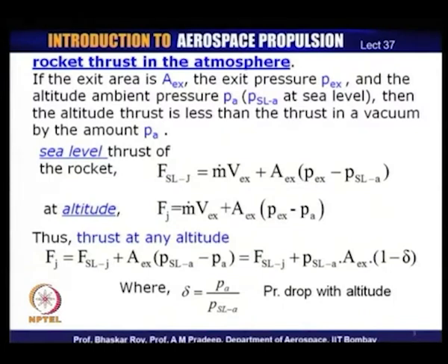The second term that you see and you are familiar with by now in the jet thrust creation, you can see the second term is dependent on the pressure that is available, or the differential pressure that is available across the exit section of the thrust nozzle.